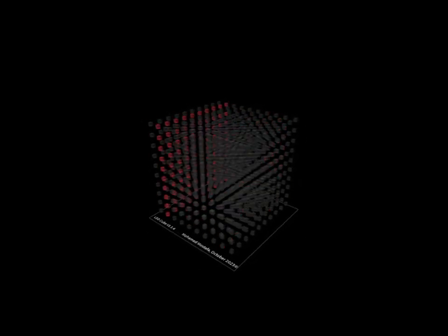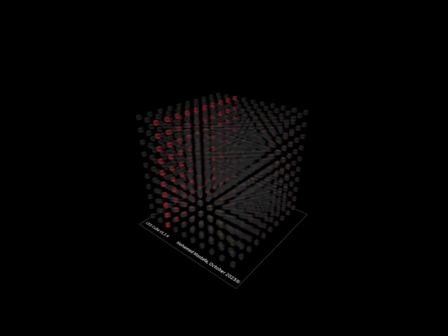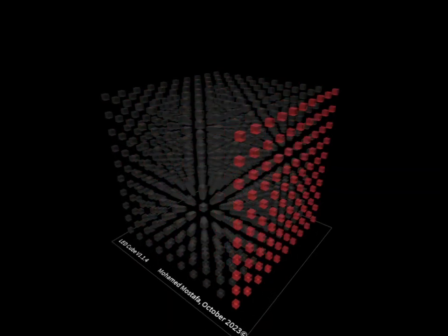By only turning on the transistor for one layer, current from the anode columns can only flow through that layer. The transistors for the other layers are off, and the image outputted on the 64 anode wires is only shown on the selected layer. To display the next layer, simply turn off the transistor for the current layer, change the image on the 64 anode wires to the image for the next layer. Then turn on the transistor for the next layer. Rinse and repeat very fast. The layers will be referred to as layers, cathode layers, or ground layers. The columns will be referred to as columns, or anodes.